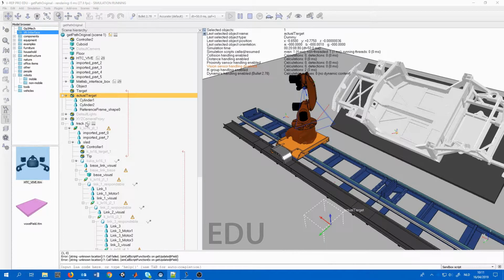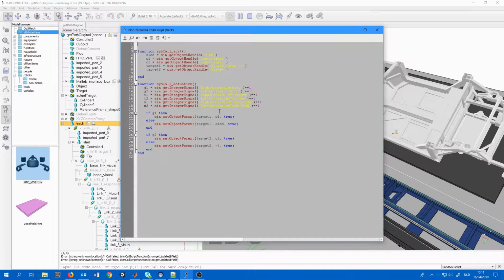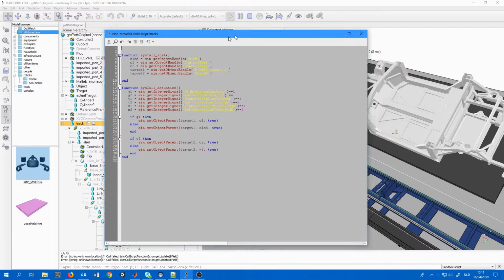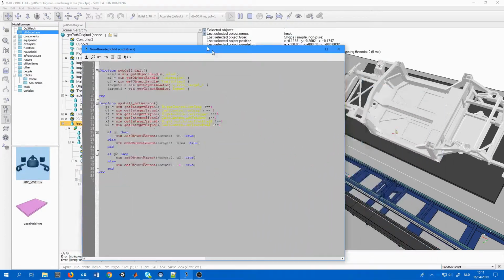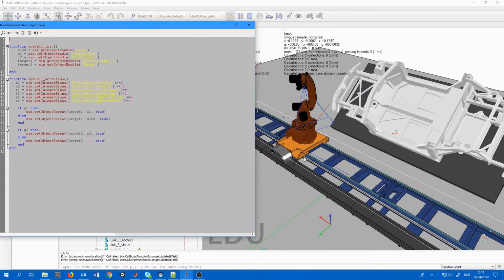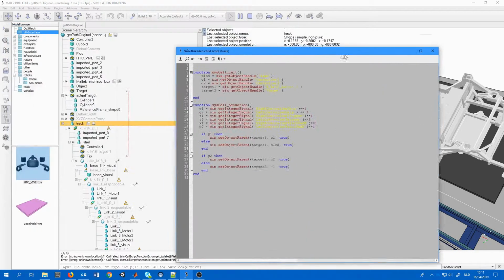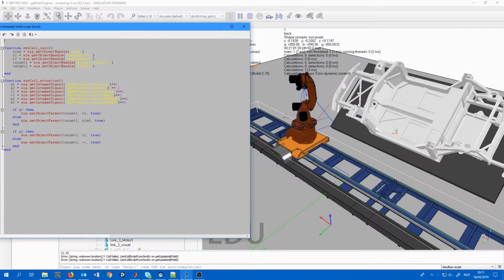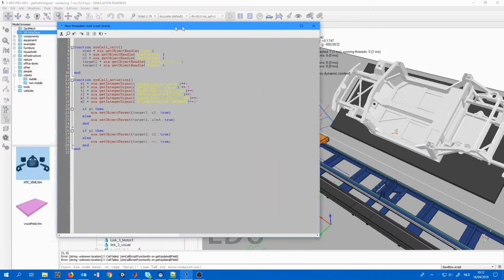Let's open our script again and first discuss a strategy. Right now, the inverse kinematics is continuously solving to the targets, and we could move the end effector by making the targets a child of the controller. So if the controller moves, then its children move with it.